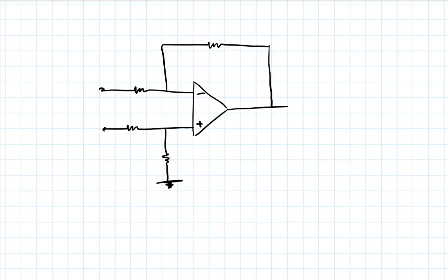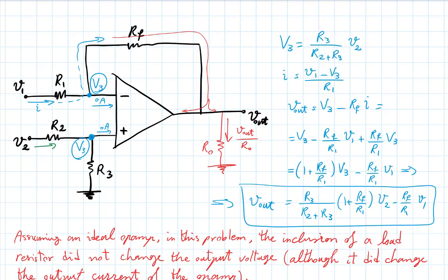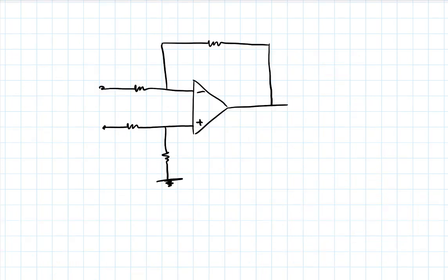Something that we saw last time. The question is, if I want to connect some V1 and V2 here, I have to make sure that whatever circuit gives me the V1 and V2 can provide these currents, the blue and the green currents, right? What if they can't? So I want to build something safer that does not impose these input currents on whatever else I'm going to be connecting to it, that is not going to load whatever else I'm going to connect to it. Something I drew last time. How about this?